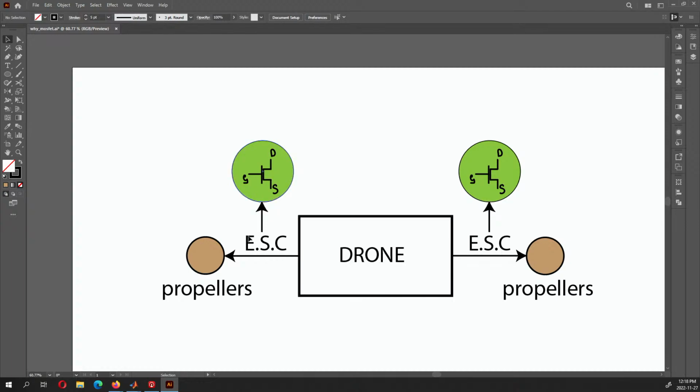And you really can't be too creative if you buy something off the shelf, because it might be very optimized for a very specific configuration, and if you change that configuration, and you don't want to use a quadcopter, you want to use, say, a bicopter or a helicopter, it may not necessarily fit your needs. You also want to make sure that the propellers that you're mounting work with your ESC, and for that you need to know whether your MOSFET can handle it. So really understanding the components that you're selecting, simulating to see whether it'll handle the current and voltage that you're really going to subject it to, is a great way to really build things from the ground up.